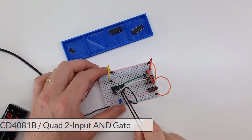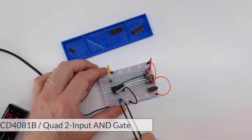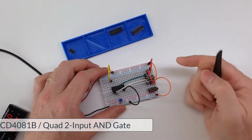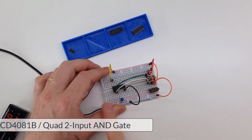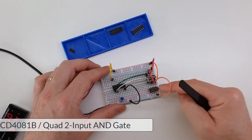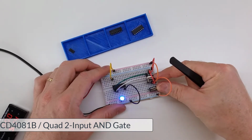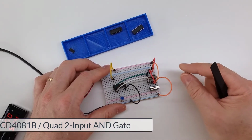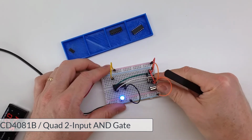There we have it on our breadboard. We've got our AND gate, we've got our 1 input and our 2 input, and then our output is just this blue LED with a little resistor on it. Here's our ground, and then here are 2 switches just as we've been wiring them up. So they're normally closed, so both of these are low and our output is low. So if we push one of them and take that high, our output is still low. If we take the other one and put that high, the output is still low. If we put them both high, then the output is high. And so that's exactly how it's supposed to work. It's an AND gate, so if both of these are high, then the output is high, otherwise it is low.